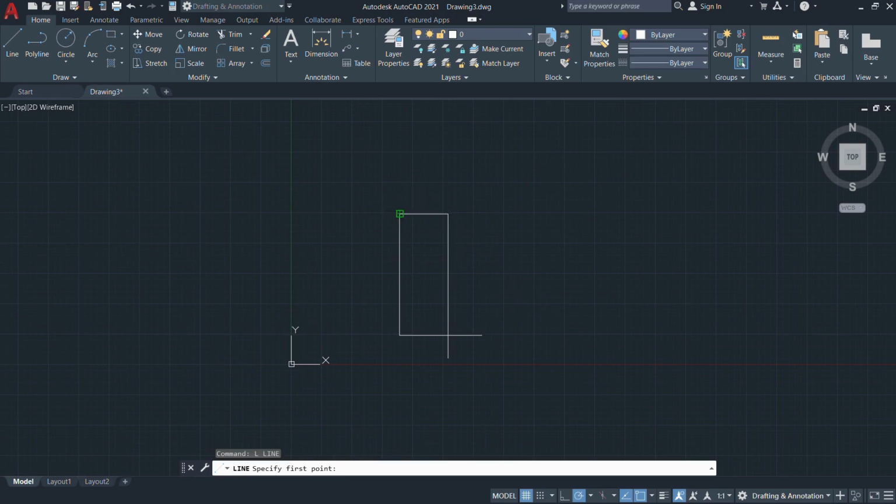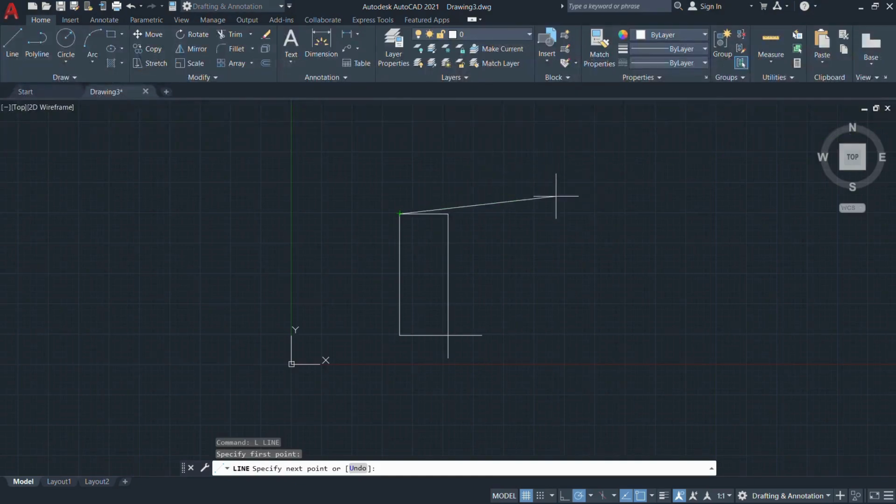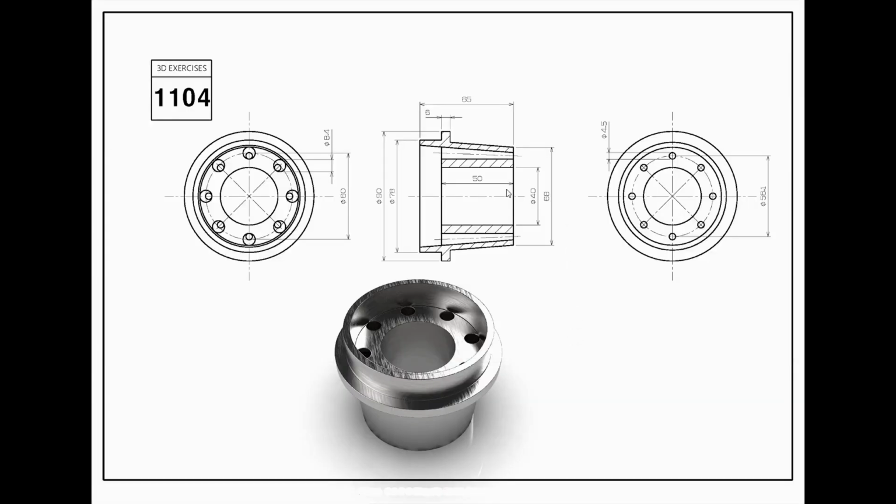Again, choose a line profile and draw from its particular center point. Look at this cavity area. That is a hole portion. It is the primary part of the overall solid body. First, we are going to draw the center line profiles. It is a 60 mm diameter, so I mention half of the value, which is 30 mm.